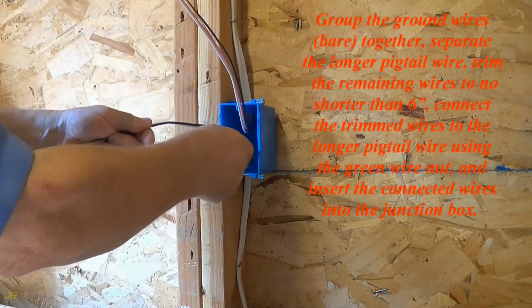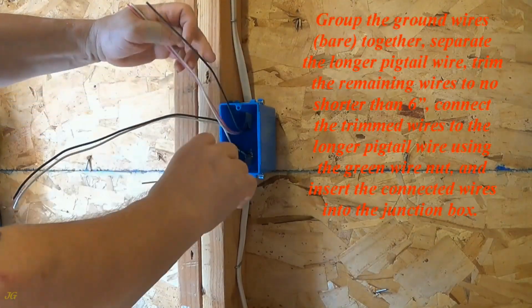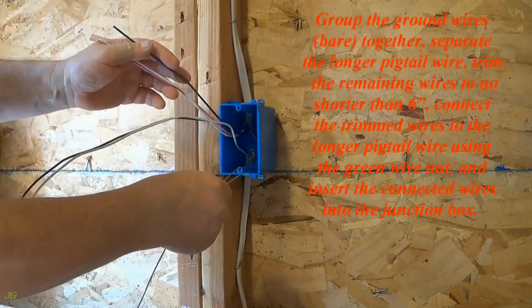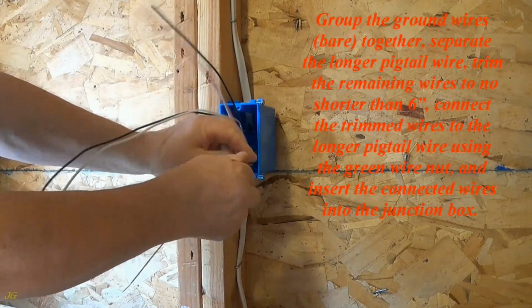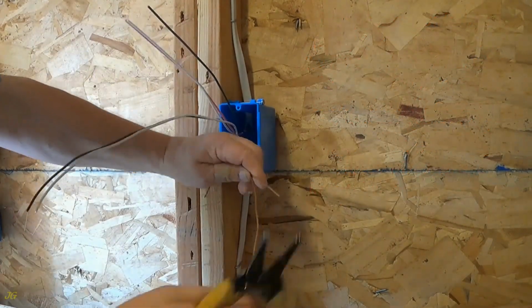Group the ground wires, bare, together, separate the longer pigtail wire, trim the remaining wires to no shorter than 6 inches. Connect the trimmed wires to the longer pigtail wire using the green wire nut, and insert the connected wires into the junction box.